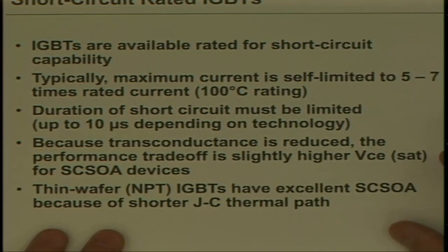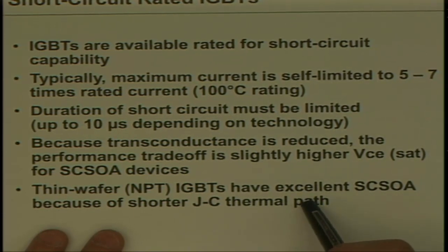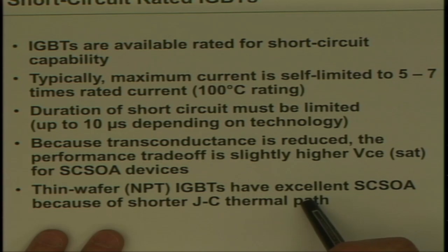One of the technology trends you'll see in IGBTs is that they're becoming thinner and thinner. Ten years ago, the wafer was 300 or 400 microns thick. Now it's maybe 50, 60 microns. It's like a piece of paper. You can fold it; when you look at the full wafer, it's amazingly thin. And if you think about it, I'll do some bad artwork here again for you.